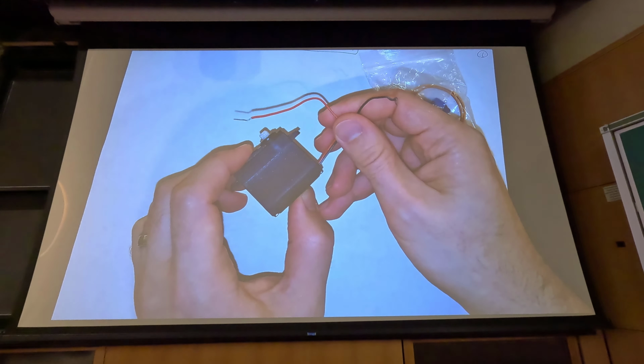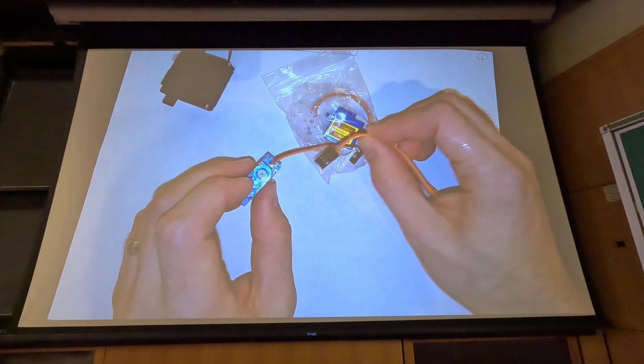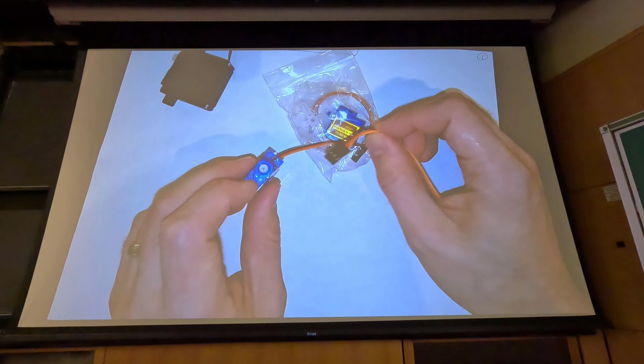These are controlled using an H-bridge like you did in Lab 3. The wheel just kind of snaps on to the output shaft here, and then I believe there's a little screw that connects it. You also have smaller servo motors. Now notice how these have 3 wires. I mentioned last time, these have a power wire, a ground wire, and a control wire that we are going to send a control signal to. We'll talk about that later today if we get there.